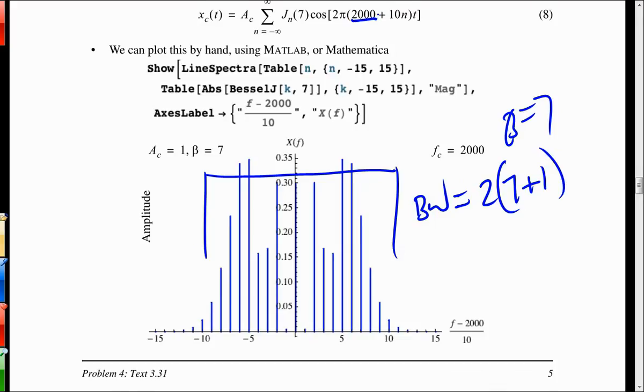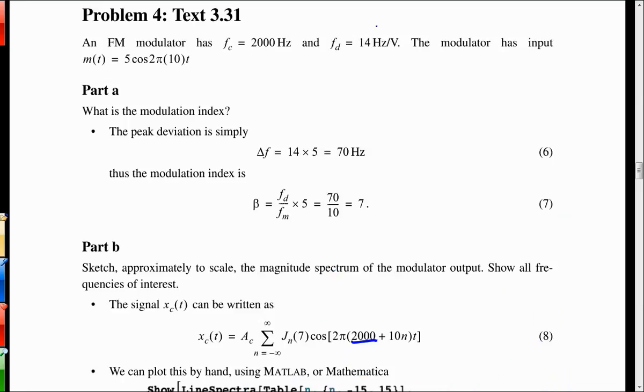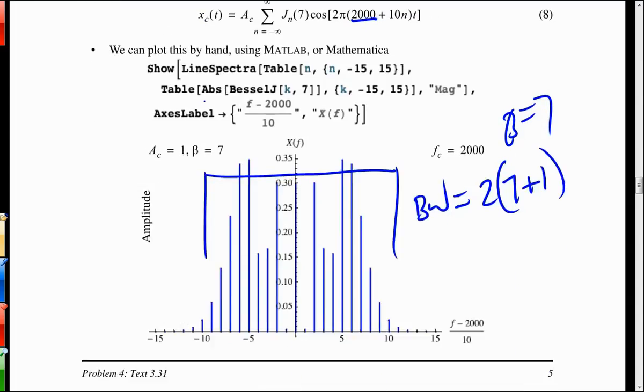And the tone frequency here is 2 kilohertz. No, that's the carrier. The tone frequency is 10. So you just have to plug that in out here. So that's 16, so it's 160 kilohertz. Did I do that right? 10 hertz. No, it's not kilohertz, it's hertz. Just hertz. Yeah, it was just 10, is that right? Yeah, that's right.